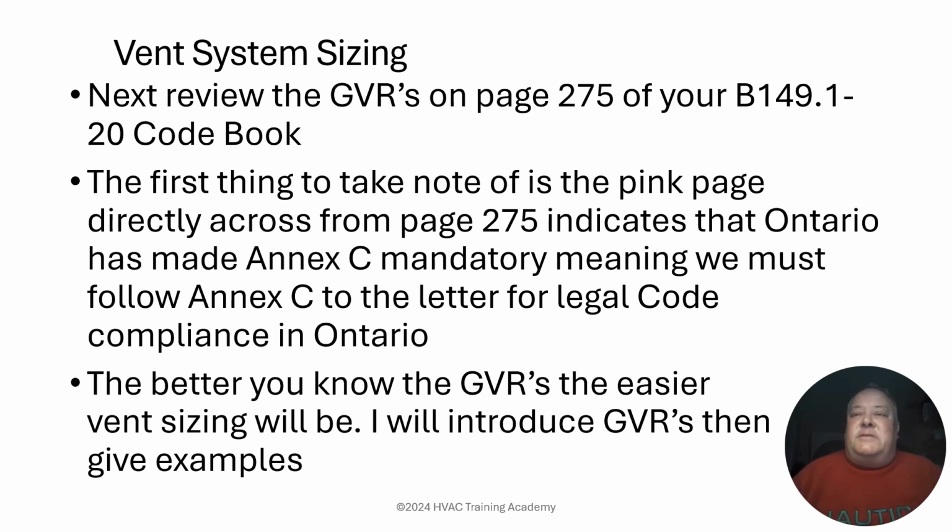The first thing that they take note of is the pink page directly across from page 275 indicates that Ontario has made the complete annex of vent sizing mandatory, meaning we must follow that to the letter for legal code compliance. The better you know the general venting requirements, the easier vent sizing will be. You can introduce the GVRs and then give some examples.